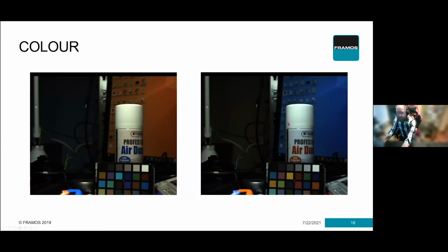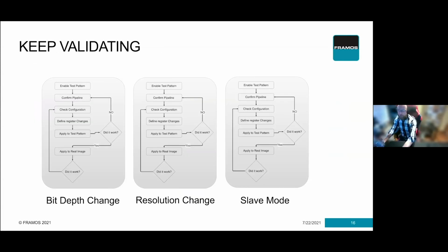These are the two sane ones where we swap red and blue. If you swap green and red or green and blue, you'll generally get really crazy magenta or very teal looking images. So that's a good hint that you've got the wrong debayering process.